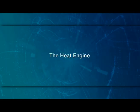The heat engine. It is a device that converts heat continuously into mechanical work. The three parts of the heat engine are: first, a source of heat of infinite thermal capacity maintained at a constant high temperature. Then a sink. A sink is of infinite thermal capacity maintained at a lower constant temperature. There must be some substance through which heat is absorbed from the source and rejected to the sink. The substance is called the working substance.